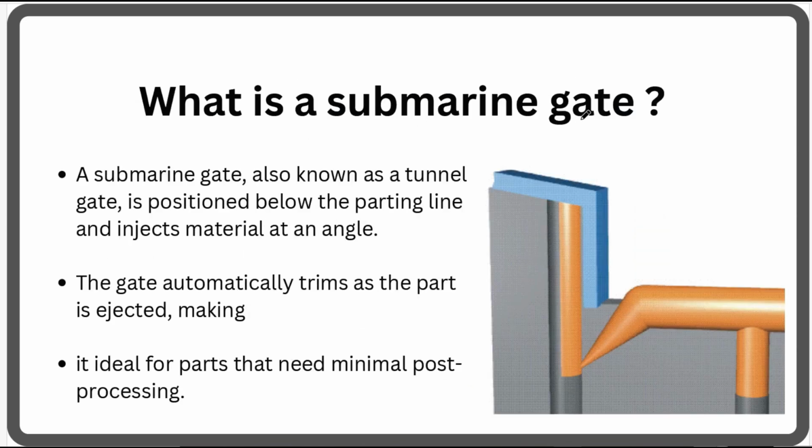So what is a submarine gate? A submarine gate is also called a tunnel gate, and it is positioned below the parting line and injects the material at an angle.